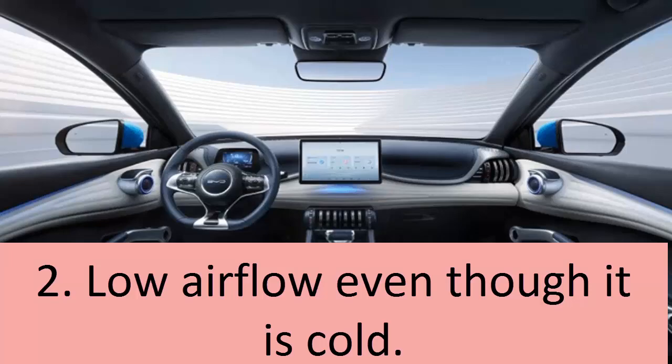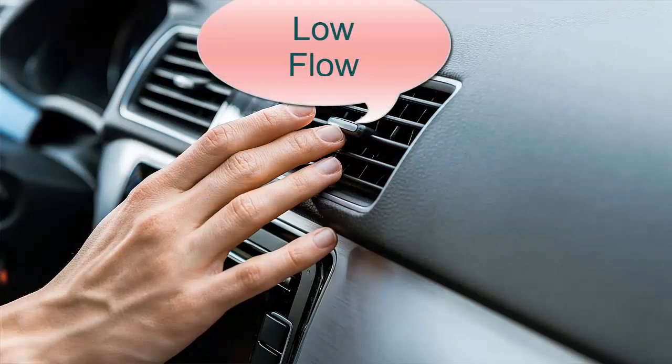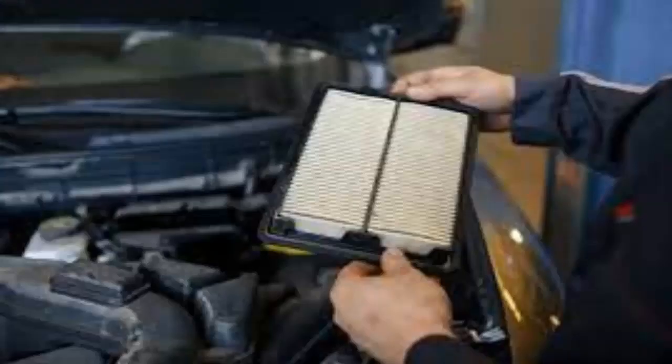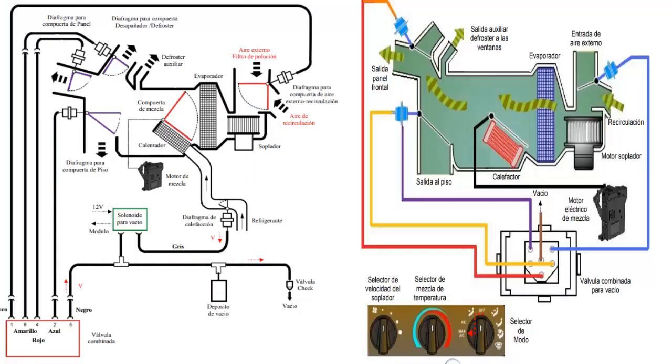As for the second failure related to the lack of airflow, when turning on the system, meaning there is cold air but with a minimal flow, the following steps are recommended. Check and replace the system's air filter, according to the car model. The lack of air may be due to an obstructed internal duct, possibly caused by a faulty air control window servo motor.